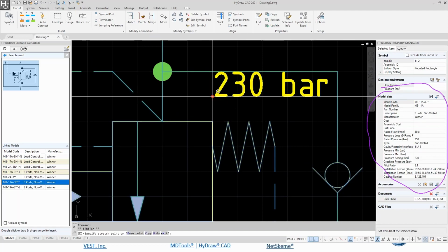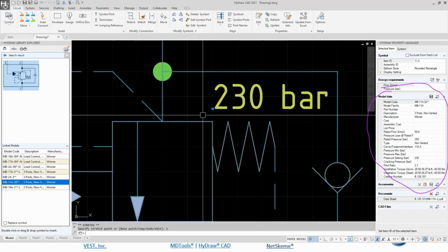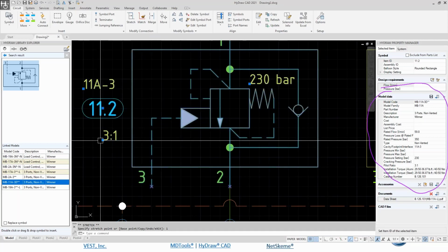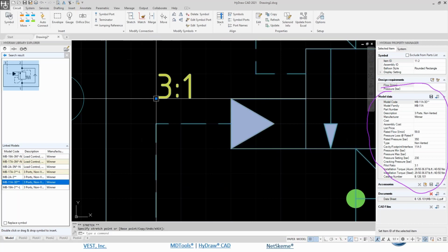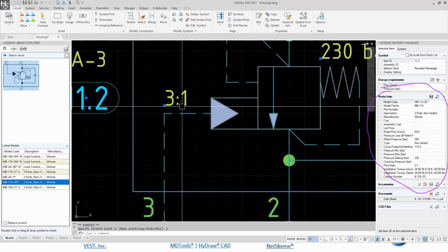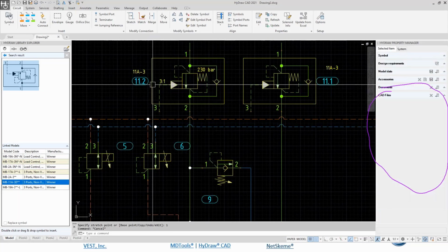Again, now you see that I have the snap to grid. So this is annoying because I want to place it in the middle. So just move it, press 1 and press enter. This is making a move of 1 millimeter down. Of course, if you are using millimeters, you press 1. If you are using inches, you will type a fraction of an inch. But this is handy because you can really easily and precisely position. Just select a direction, type a number and press enter. It will move that symbol or entity just by that amount that you type with the keyboard.